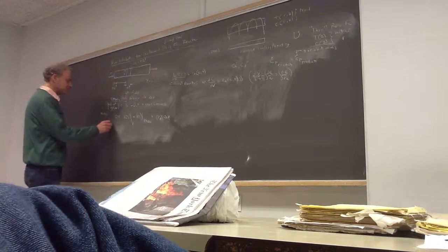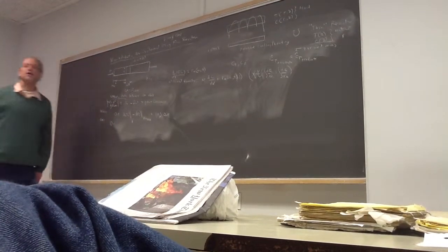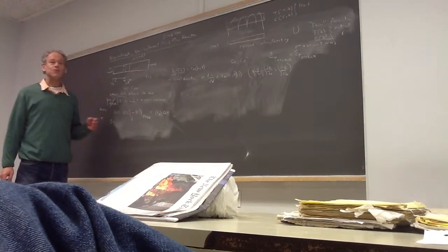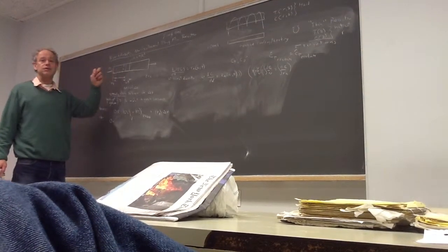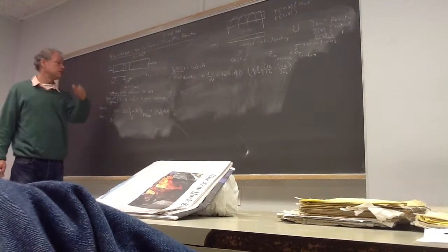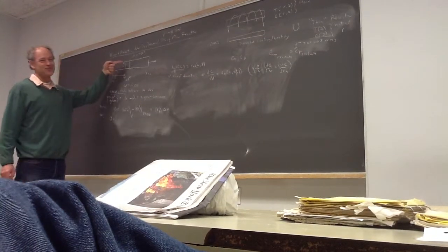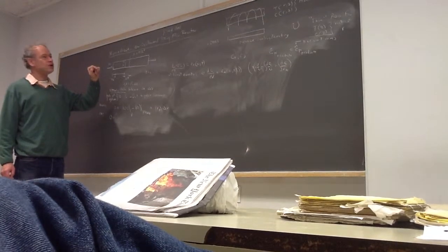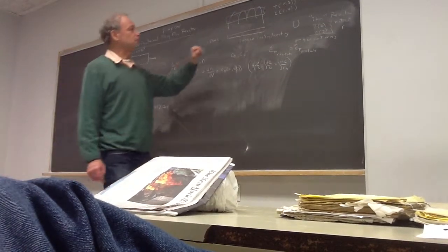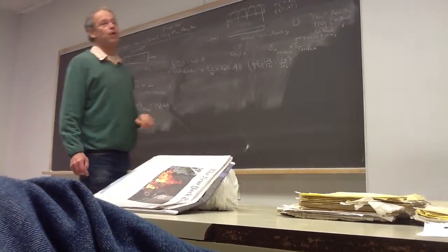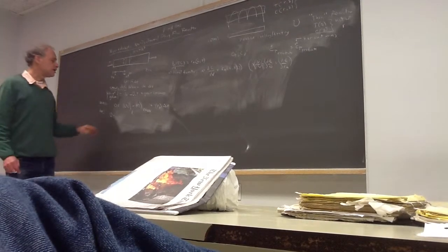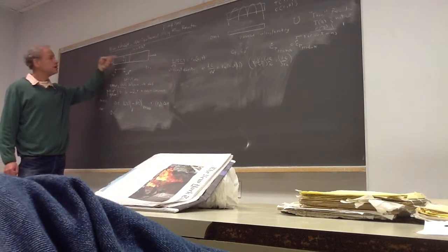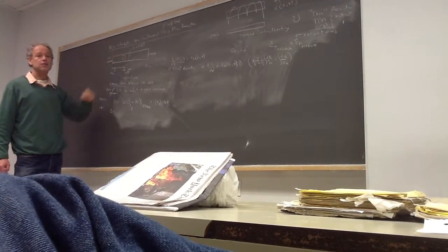Okay, so now let's do the heat balance. Again, steady state. What is the heat going in here? Here, there's no external Q. The only Q I have is U, the passive cooling. But I'd like to know, by virtue of the flow mixture, what is the enthalpy in?